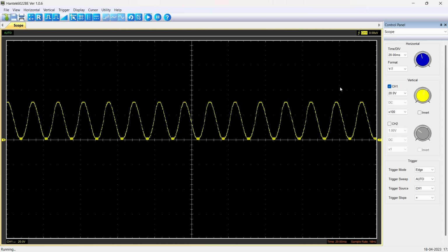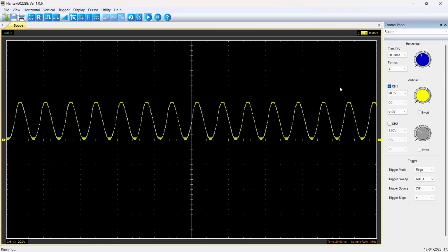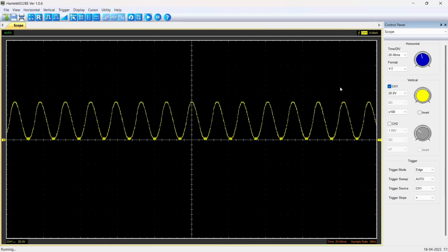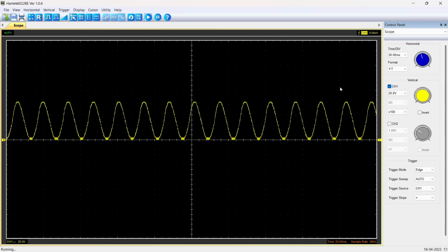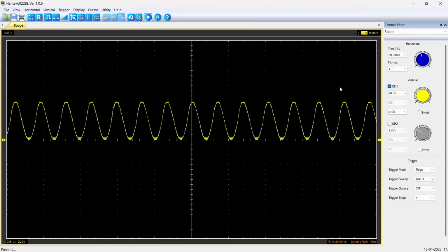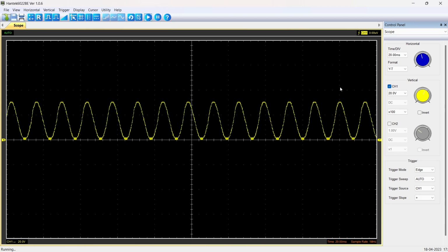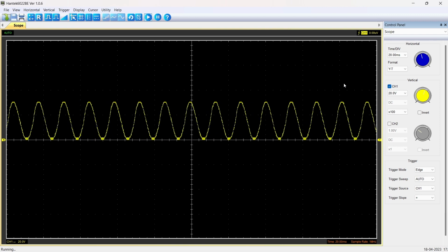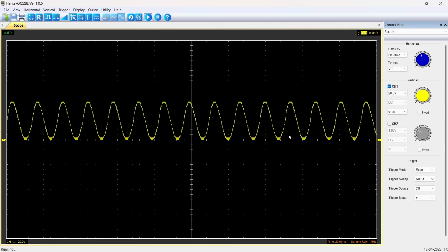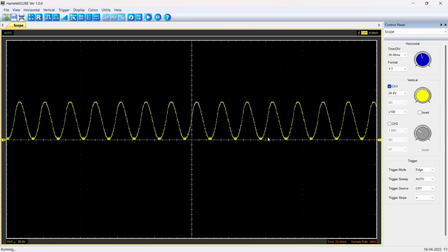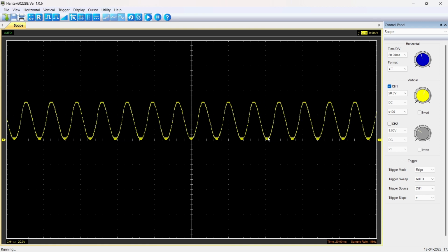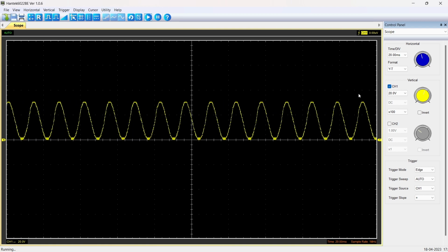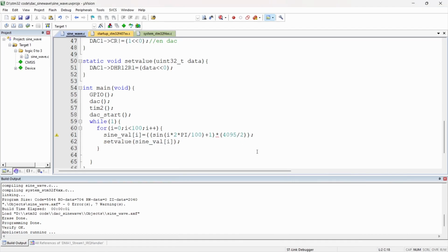Now we have created this sine wave. Okay. So what is the next thing we are going to do is we are going to convert this. I have already converted this audio file. It is 1 minute, 2 seconds of audio length. So I have converted it into a digital file already. So what I'm going to do is I'm going to send those digital values to this PA4 pin, which is a DAC output. So this DAC output is going to get into the speaker, and before getting into the speaker, we will see how the waves work in this digital oscilloscope.